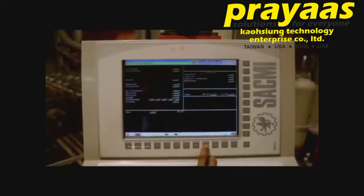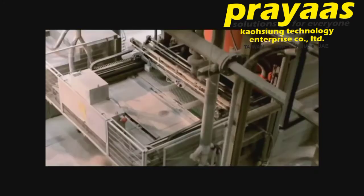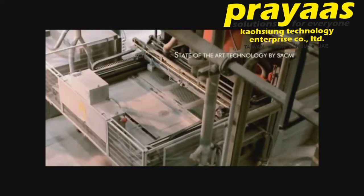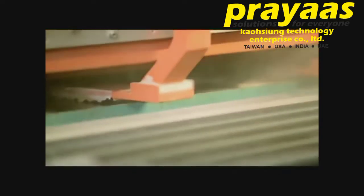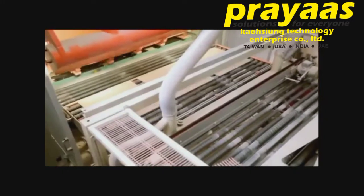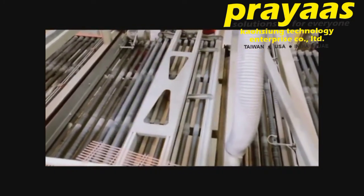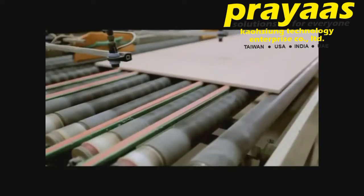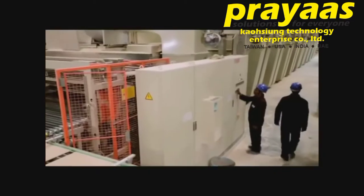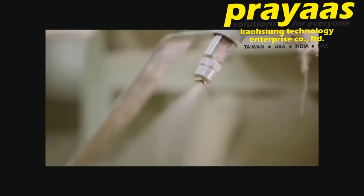Made by Sacmi, the world leaders in tile technology, our fully automated tile press is capable of shaping tiles in a range of sizes and shapes. The machine presses the powder at 400 to 500 bars of pressure to create a raw green tile. This green tile is then processed in a dryer, completely removing all moisture content, making it ready for the processing that will truly give it color and finish.